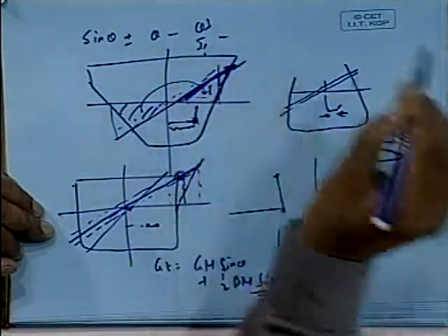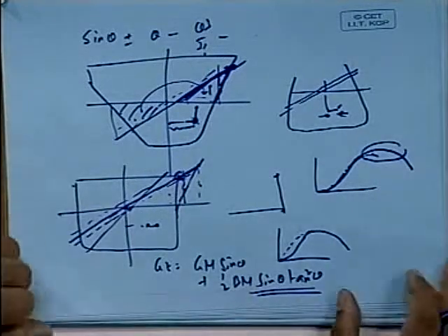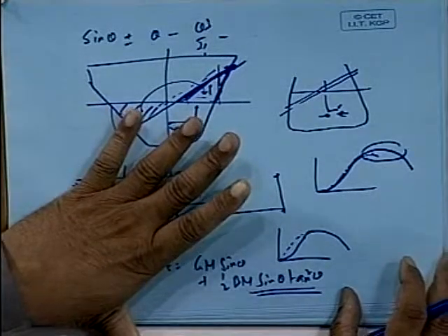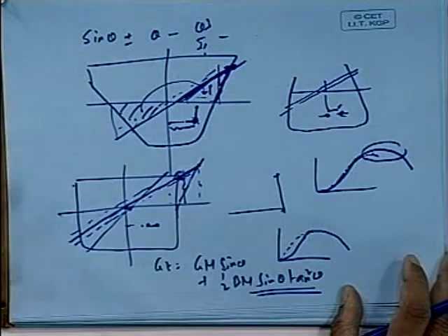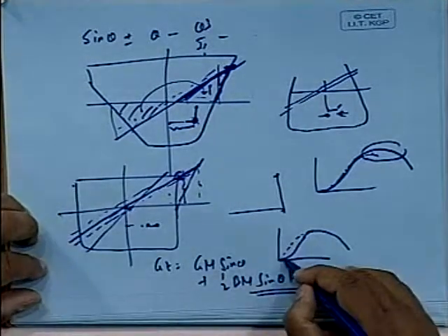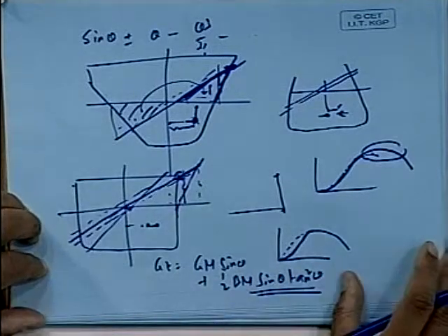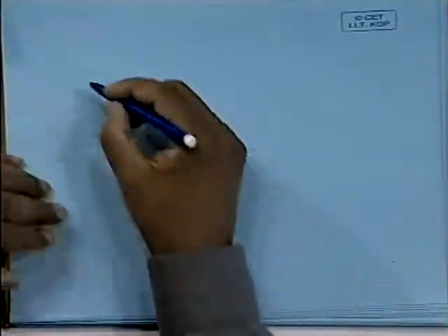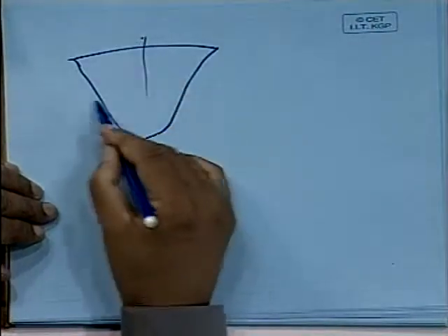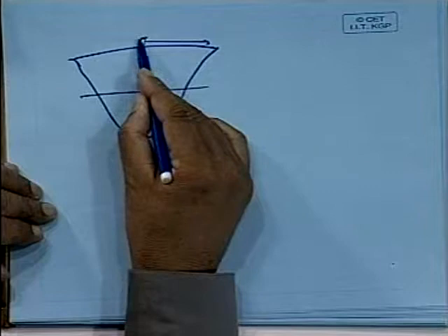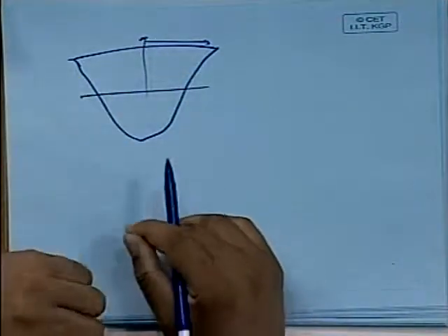There is a formal formula there like this. You will easily see that. I am not going into the mathematics of it, but you can easily see that by an expansion, even up to a small angle. But the point here is that this is interesting, because this happens to all ships, and this is one of the reasons, from stability, why most ships have this kind of flare preferred. Of course, not only one, because people want to have larger deck area, but flare always gives a higher stability.